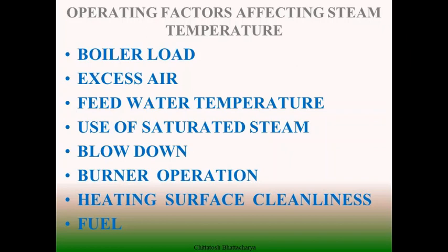Another issue is the heat transfer arrangement across the boiler, because heat is transferred through different heating surfaces, heat traps, and their cleanliness, whether they have fire side corrosion or water side corrosion, so these also affect.